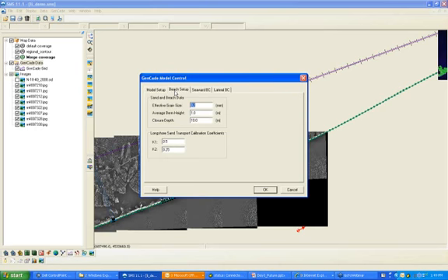We're going to go to our beach setup. We're going to modify our effective grain size to 0.3. Our average berm height is going to still be 1, but we're going to change our closure depth to 8. We're also going to modify our K1 and K2. We're going to change K1 to 0.3 and our K2 to 0.15.